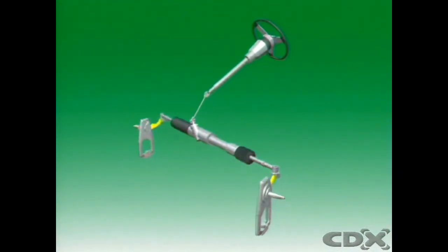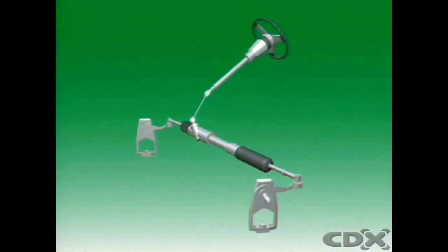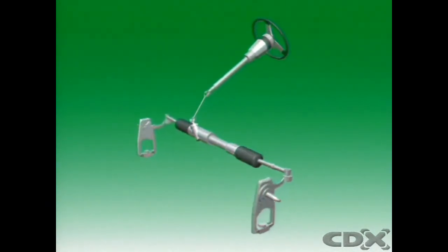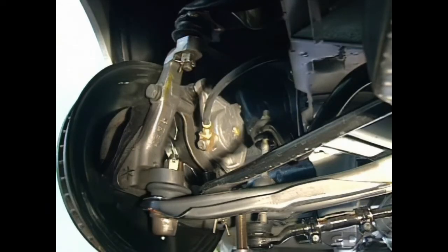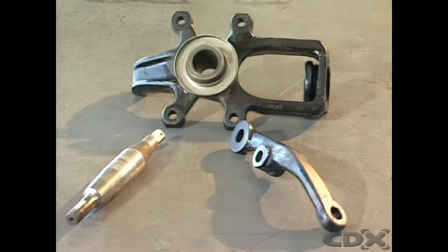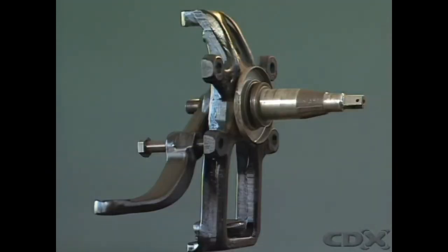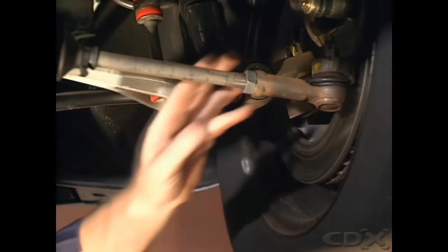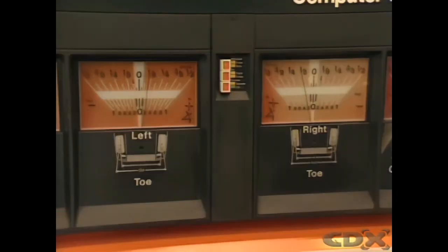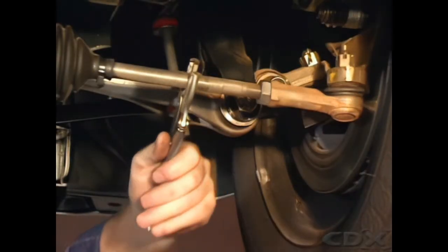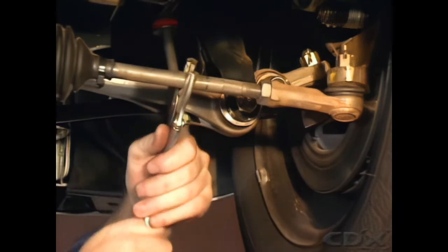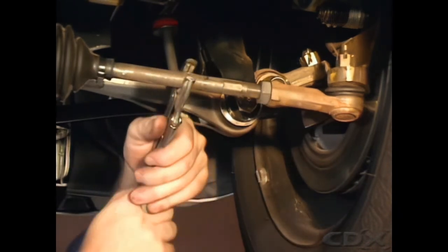The steering lever or steering arm is linked to the tie rod or track rod by a flexible ball joint that allows for suspension movement and steering rotation. The lever, the stub axle, and the stub axle carrier can be forged as one piece and can be referred to as a knuckle. They can also be made as separate units and assembled to form one piece. Each steering system makes provision for adjustment of the linkage to achieve the manufacturer's recommended toe setting. The track rods or tie rod ends are threaded to provide for their lengthening or shortening.